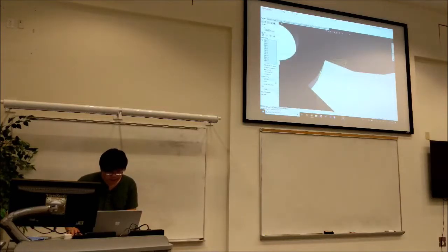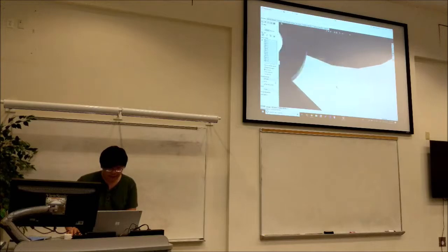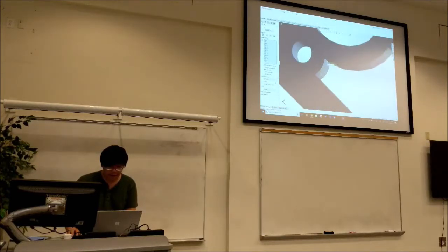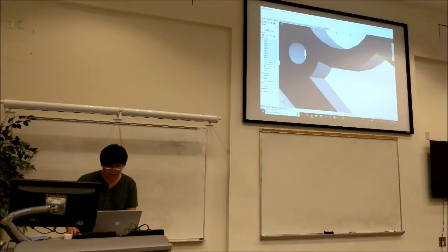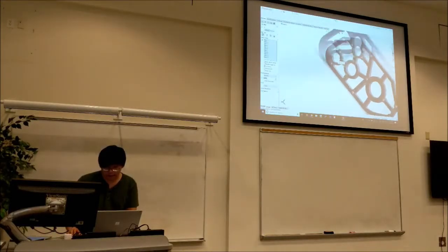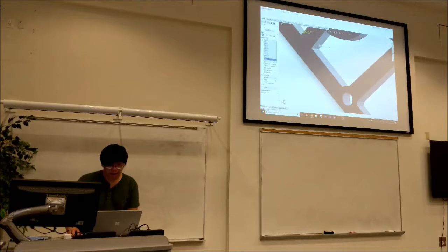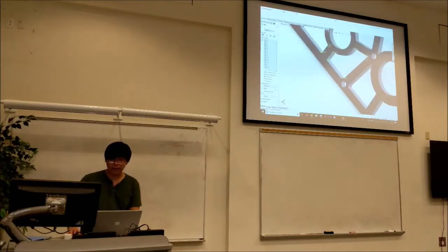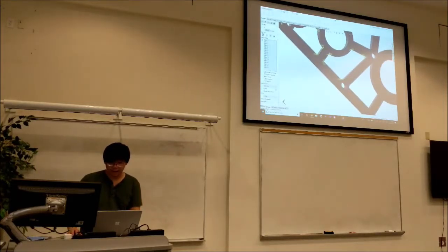And then you can see for this, it looks correct, but it actually isn't. They're crashing into each other, so we can just deselect these, and then we'll use a face fillet later to go in and fillet that. We can click that, and then we'll do this, and it'll automatically fill in this pocket. That all looks fine.